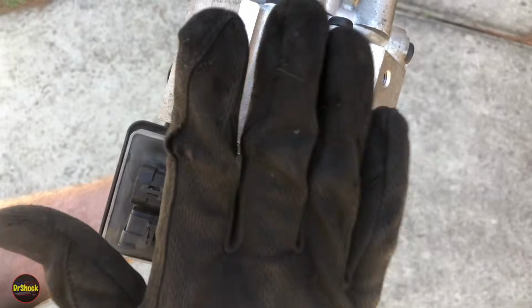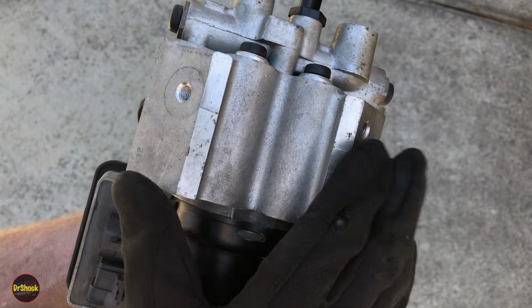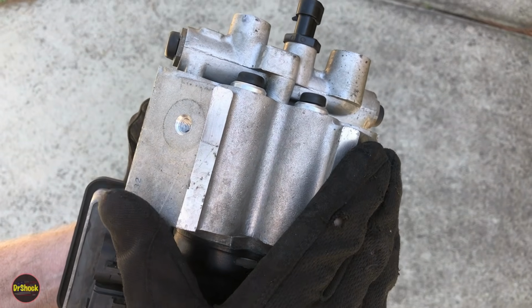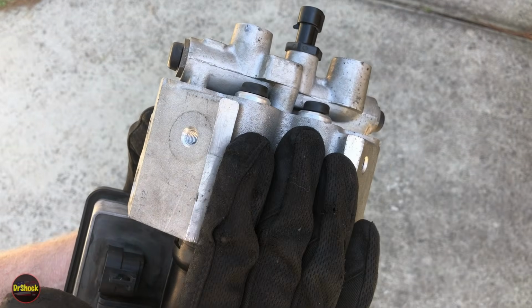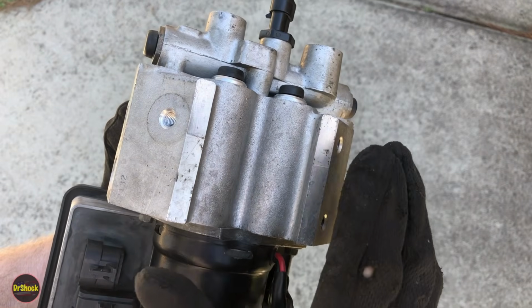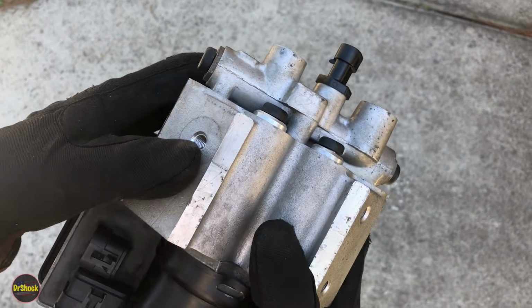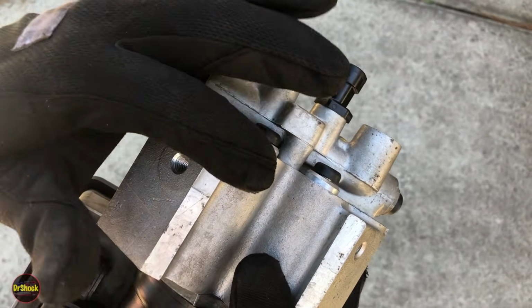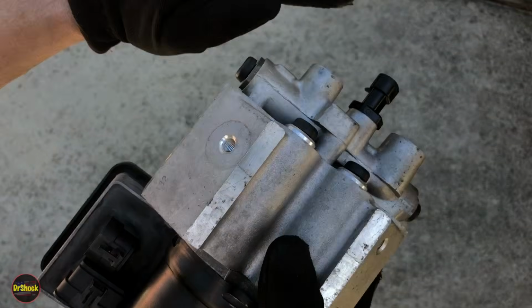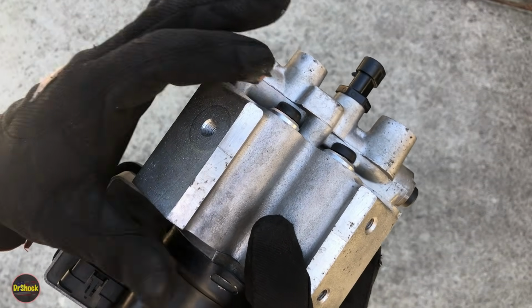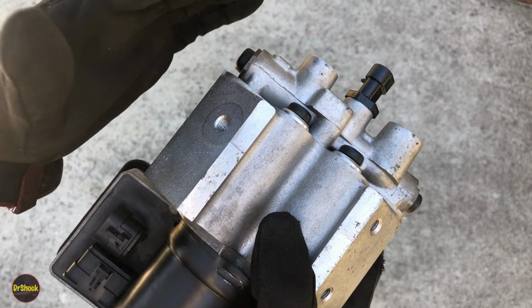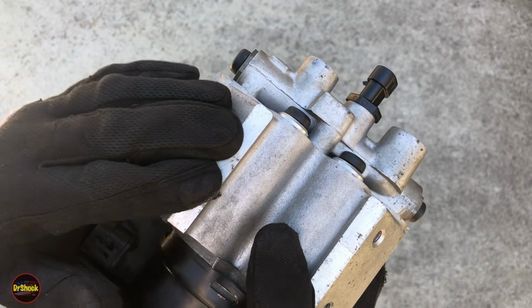All right, guys, when it comes to the other problem in this video with the BPMV, there's not a specific diagnosis. I'm going to tell you what the situation is, though. The BPMV was replaced several years ago because the pedal went to the floor. That's one of the things that these brake pressure modulator valves can cause, because you can get a situation inside where the internal valves are not closing all the way, and so you don't have any back pressure. When you push the pedal down, it just goes straight to the floor. You've got to eliminate other problems that can cause that and are more common, like a problem with the master cylinder. But if you've eliminated everything else, it's usually going to be the BPMV.